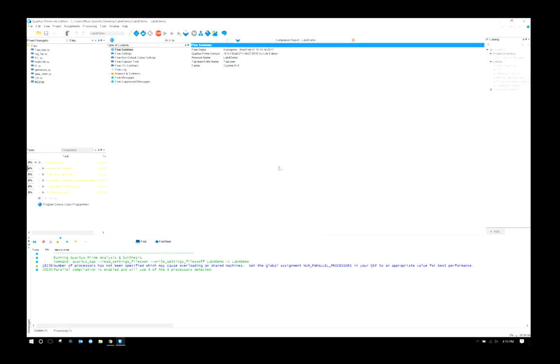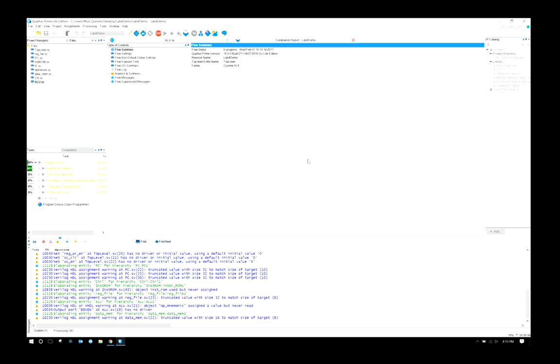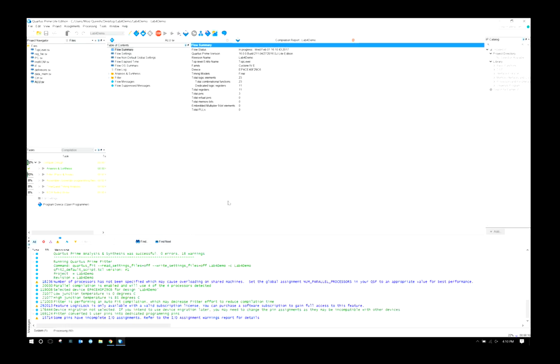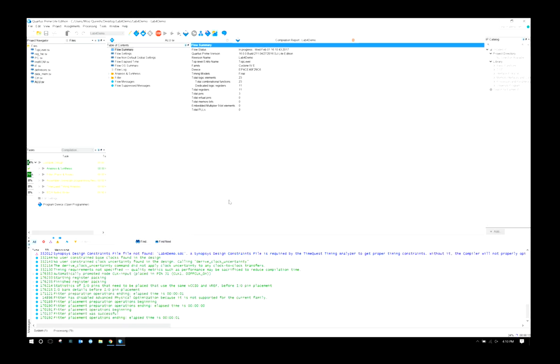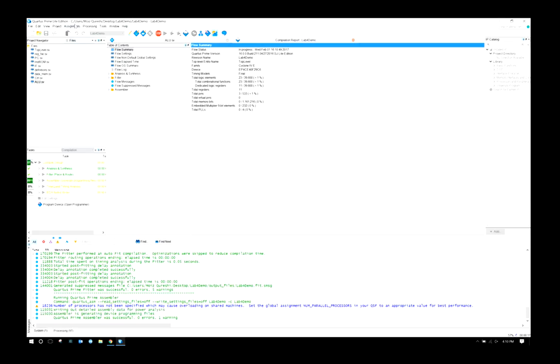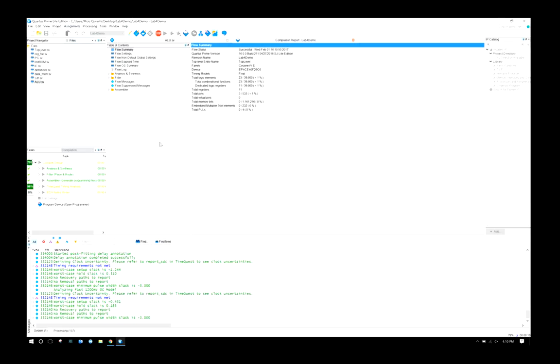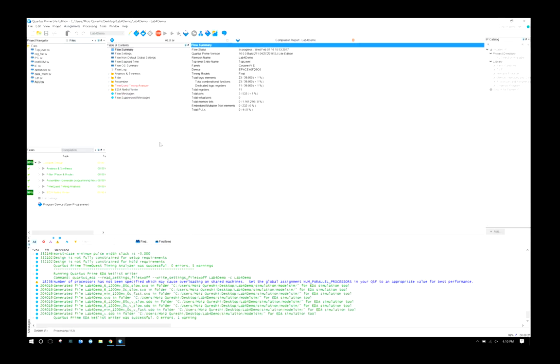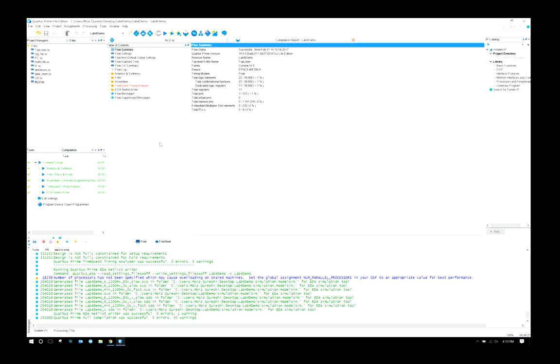So if you don't have a really, really crazy computer, your computer might get really loud and sound like it's trying to put out a fire, totally normal. So what you can do for that, I can show you another trick. Most computers are multi-core these days. Everyone's got like a dual-core or a quad-core system. When you download Quartus, it's set to just use one of those cores.